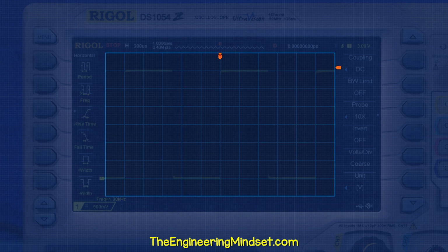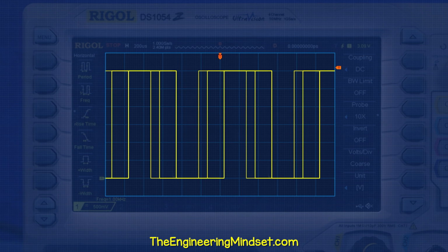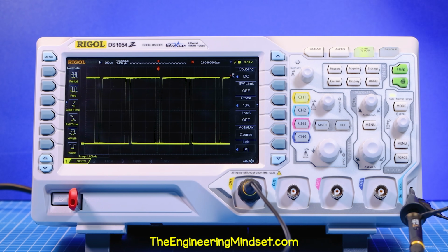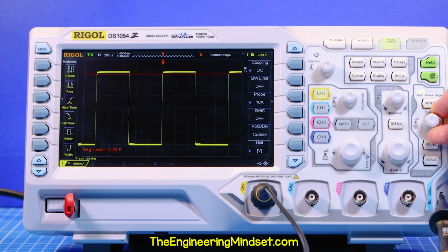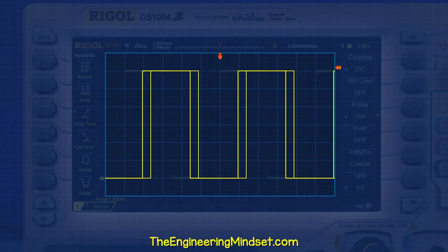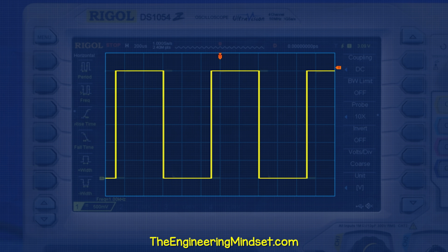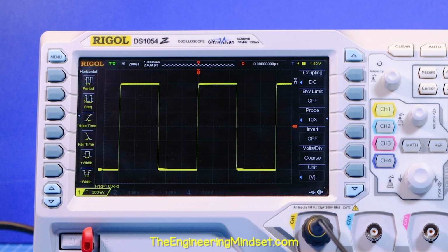Here we can see the signal has refreshed at random places. That's because the oscilloscope doesn't know where to show them. Press Run and then bring the trigger level down until the signal stabilizes. The signal is continuously refreshing. It will overlay the new measurement on top of the previous, and it will align them between these 2 points. This lets us see the signal clearly instead of just a random mess.